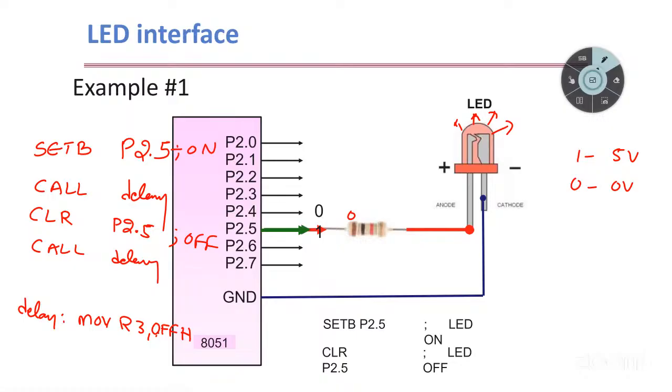If you give FF directly without putting 0 before it, the processor will treat FF as characters, so it will display a syntax error. You can't move a character into a register. The ASCII value of a character we can move to the register, but the direct character we can't move.